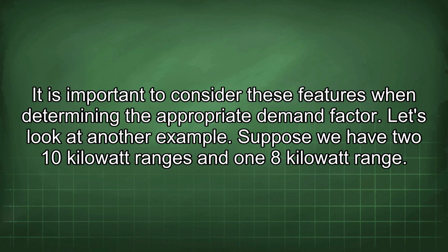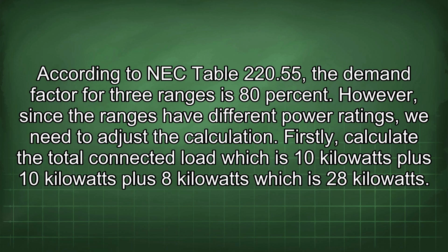Let's look at another example. Suppose we have two 10 kilowatt ranges and one 8 kilowatt range. According to NEC Table 220.55, the demand factor for three ranges is 80%. However, since the ranges have different power ratings, we need to adjust the calculation.